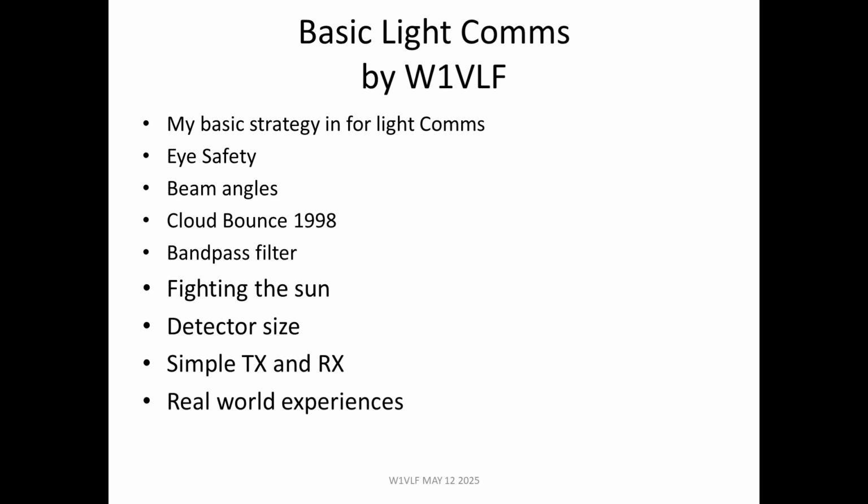Detector size is important for a bunch of reasons. Capture area and being able to actually aim, because some of these receivers, depending on the size of the lens, the focal length of the lens, and also the detector size, you have a beam width of roughly a degree or two. And that makes pointing, until you get used to it, sort of like pointing a 10 gig dish, only probably 4 times worse. But you get used to it at some point. You get a feel for being able to point this thing.